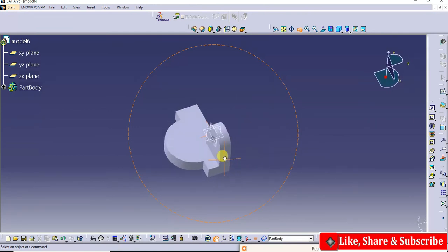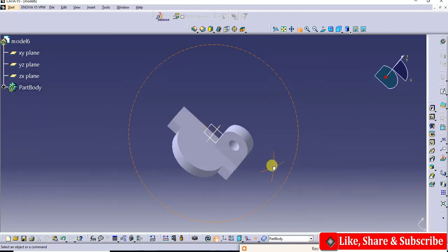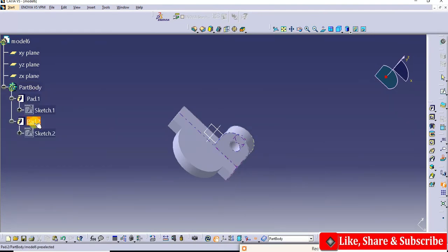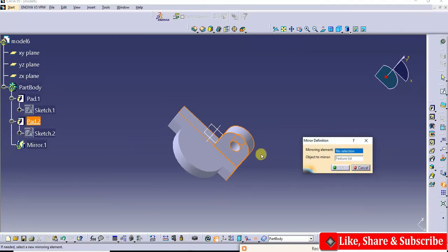Now what I do, I'll use the mirror command to mirror this feature on this side. So I'll go for the mirror command here. You select the part, you can select the part here itself, or you can go in the CATIA tree and select this feature, for example. Next you select the plane.